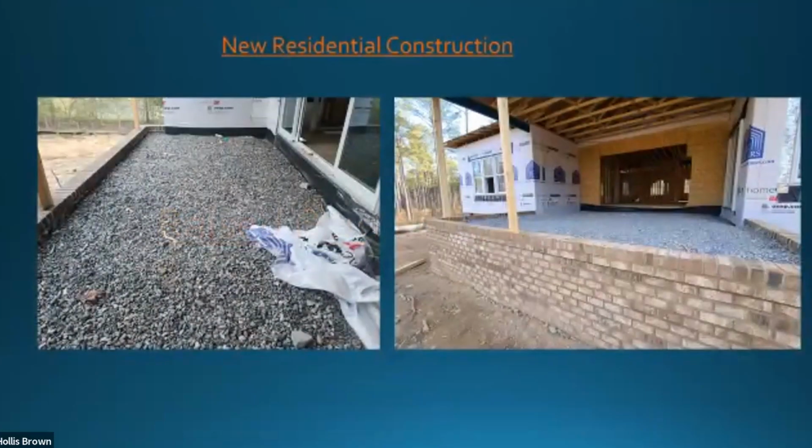So this is something I write almost every day, and this is one of those battles I have with builders that they never listen to, and they always insist that it doesn't happen on their house, and I'll see their house in 5 years, and it happened. They'll fill these big porches full of gravel, and they claim that gravel is zero compaction, which maybe from an engineering standpoint it's supposed to be, but still the concrete settles, and it almost always rotates towards the house in a few years. And then you've got to use a concrete jack to pump it up.